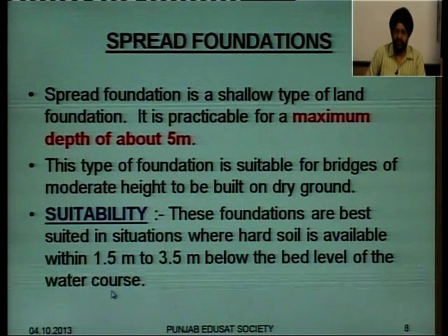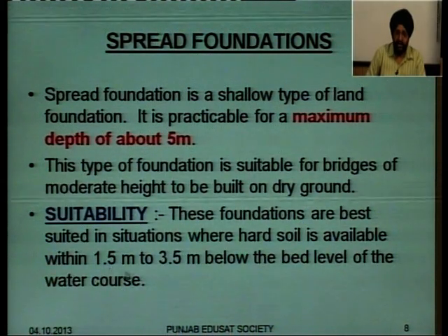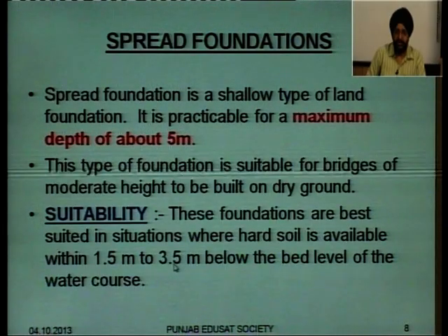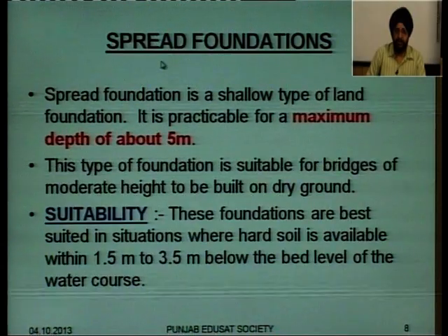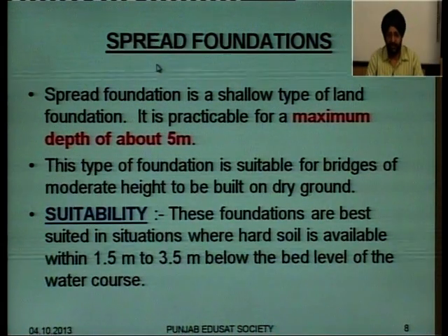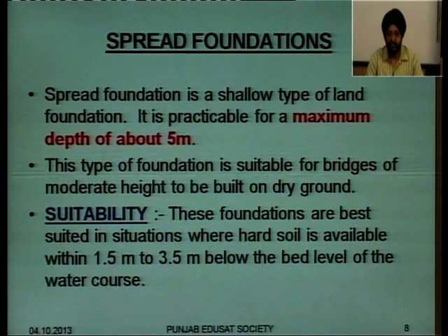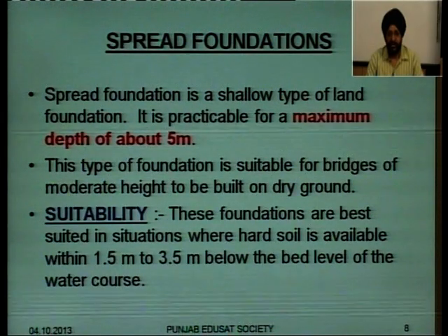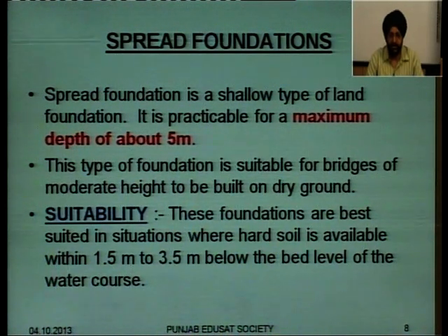Watercourse means it may be a river. So, below the bed level of the river from 1.5 to 3.5 meters, and with hard soil, these spread foundations are the best. So, these are the three different conditions. We need a hard soil, a limited depth, and these foundations are the best for moderate heights of bridges.